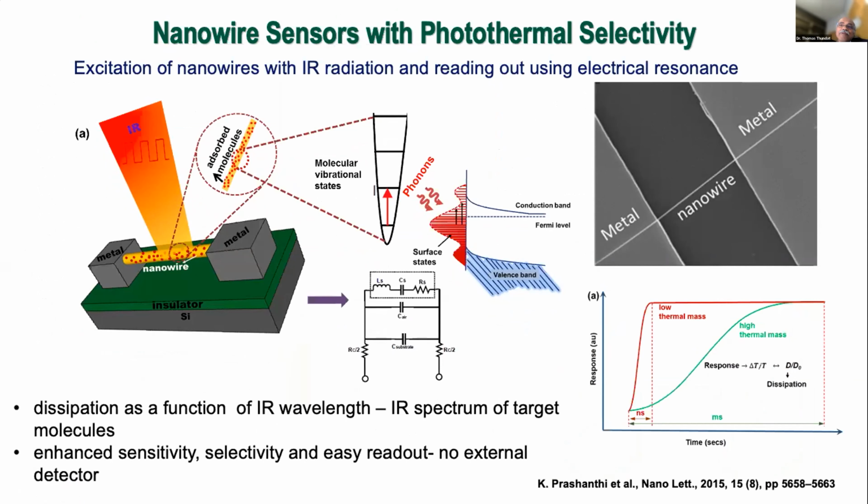So now what we can do is the same thing, but measuring the mechanical resonance becomes harder because the wires are so narrow. A nanometer-size wire, this is maybe a micron, a couple of microns. I don't exactly remember the radius of this thing, but it's very difficult to focus light and get the mechanical resonance spectrum. But what we can do is look at the electrical resonance. We can make a lumped oscillator model, and then measure the electrical resonance.